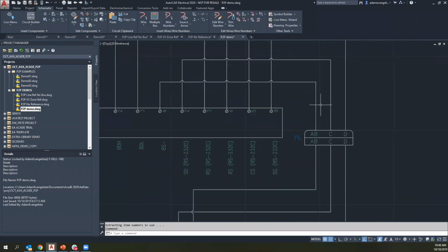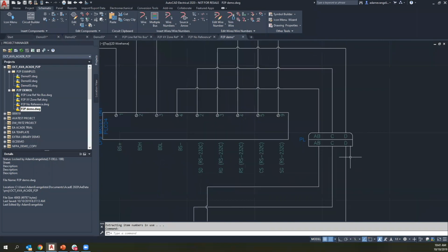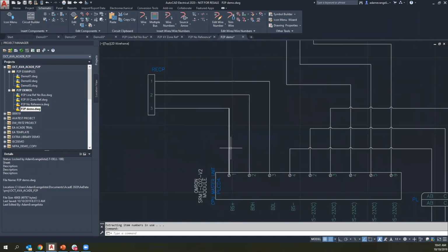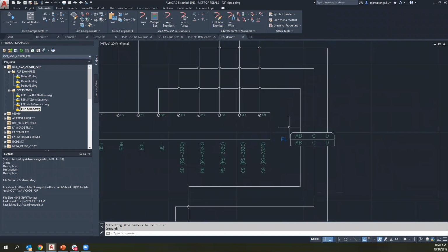So notice that the wire crossings are going to automatically adjust to show up there. In this case, I placed it a bit to the left. So the first pin, the A pin, got moved to the side. And then the B, C, and D are the ones that ended up getting the connections for this parametric insert right here. Okay. And so, yeah, the connections are really great. And again, there's a lot of flexibility, right? I can either place the connectors first, I could place the wires first if I want to, and I could go back and insert them with a lot of extra flexibility and intelligence, okay?